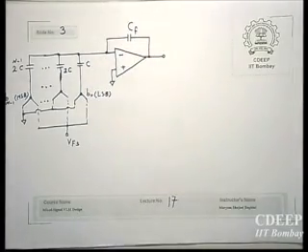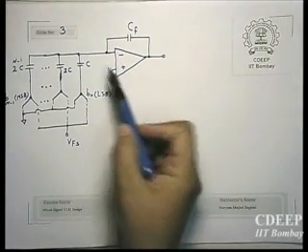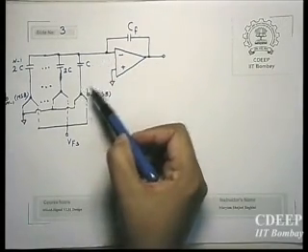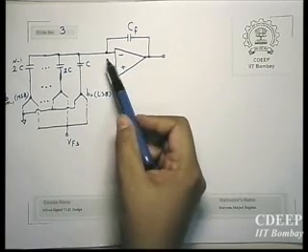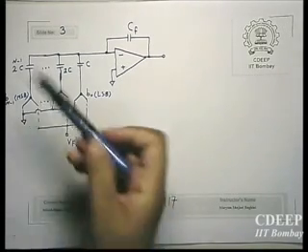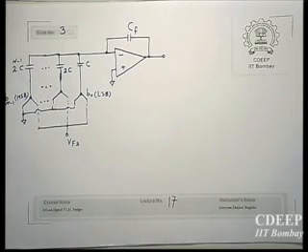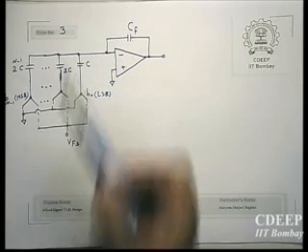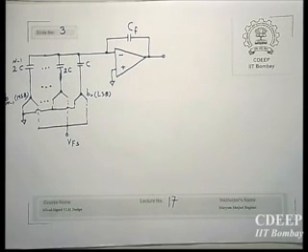Therefore, now all internal nodes, as you can see, except output voltage, are connected either to ground, V full scale, or virtual ground. So this will help to avoid the effect of parasitic capacitances, unless we have parasitic capacitances which may be parallel between these two nodes. If this happens, then we cannot do anything with that. That is a part of the capacitor. But if there are capacitances between this node and ground or between this node and V full scale, those will get shorted. Therefore, it doesn't create any problem.